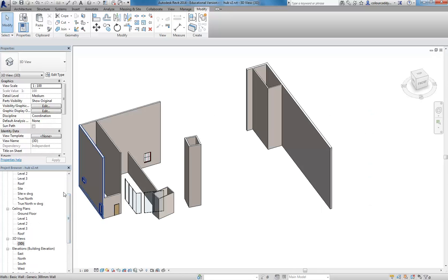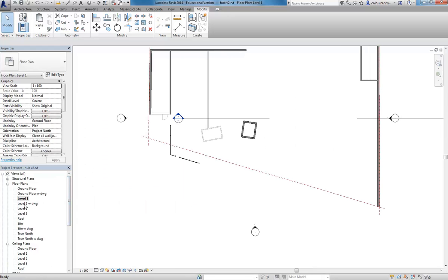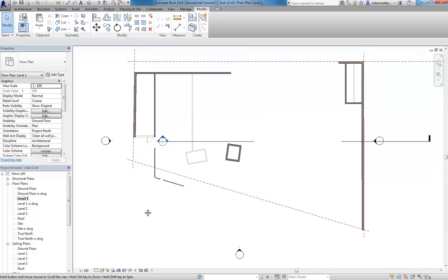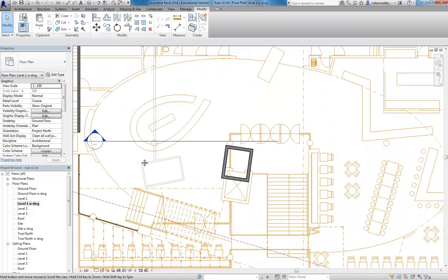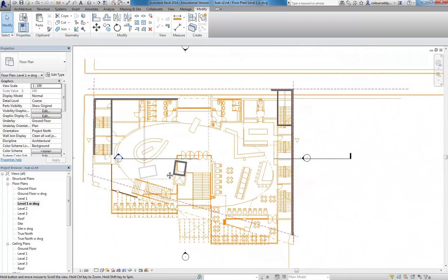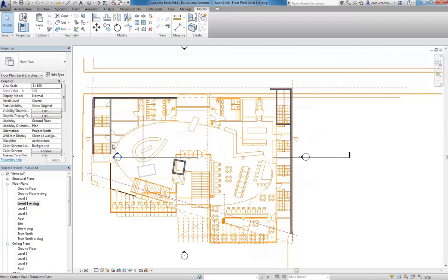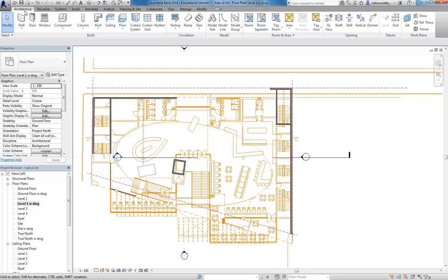And so I might just quickly show you a floor and finish this one there, because you've probably been thinking of the levels as floors. It's important to realise the floors are, of course, a separate object. So with this first floor here, it'll help a lot if I've got that shape of the floor drawn. That defines the balconies and everything. So on the Architecture tab, there's the floor tool. Let's make sure that I line that up properly.